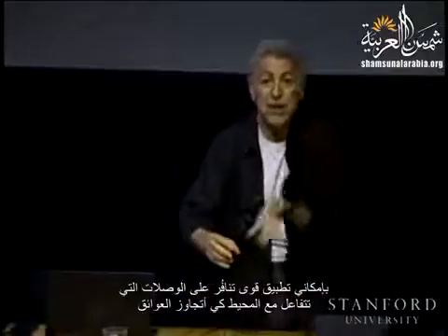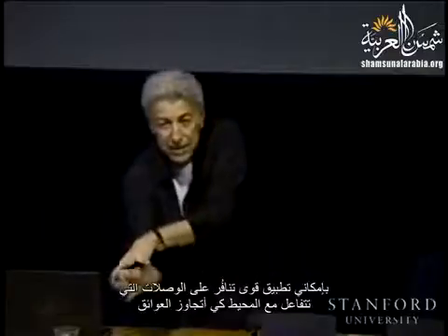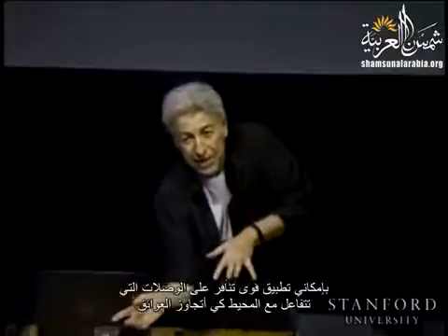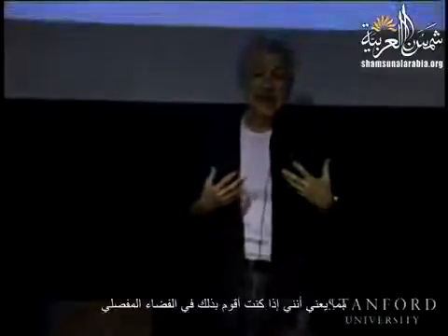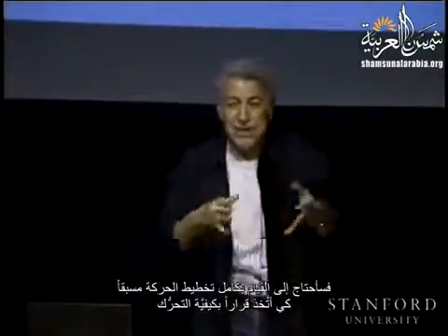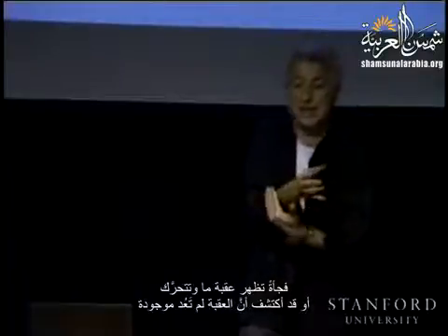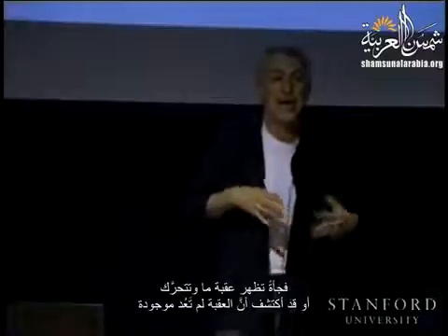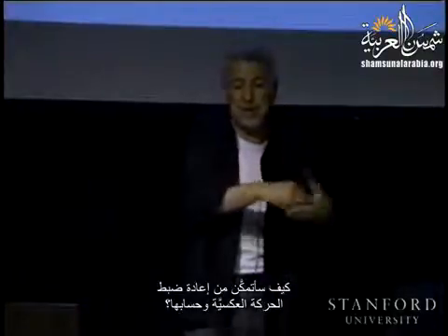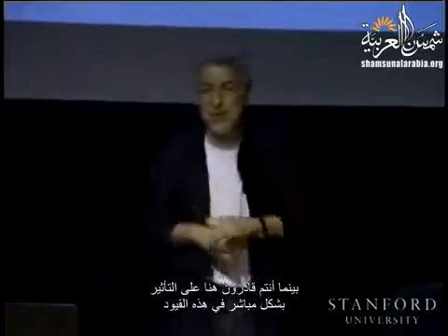Now I can apply repulsive forces on those different links that are interacting with the environment to move them away. Which means that if I was doing this in joint space, I would need to do the whole motion planning ahead of time to make the decision about how to move. But suddenly an obstacle comes and moves, or I discover that this obstacle is not there. How can I readjust and recompute all the inverse kinematics? I would need to do replanning in real time. Whereas here, you are able to directly affect those constraints.